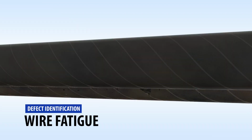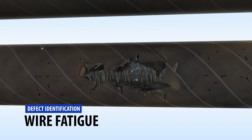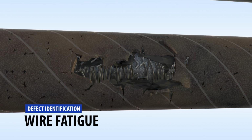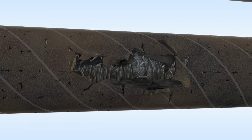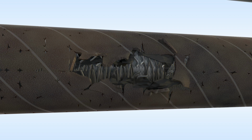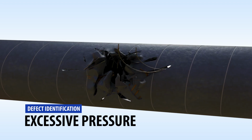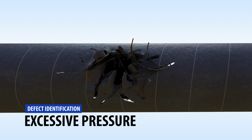Wire fatigue. In the initial stages, the wire damage will not be able to be seen. It can be seen from the image that the outer cover has deteriorated. The reinforcement wires show signs of mechanical damage and are broken. Look for signs of excessive rubbing or chafing of the hose against sharp corners, brackets, incorrect routing, or the wrong size clamps. Excessive pressure. It can be seen from the images that the outer cover and reinforcement wires have been ruptured in an outwards direction.